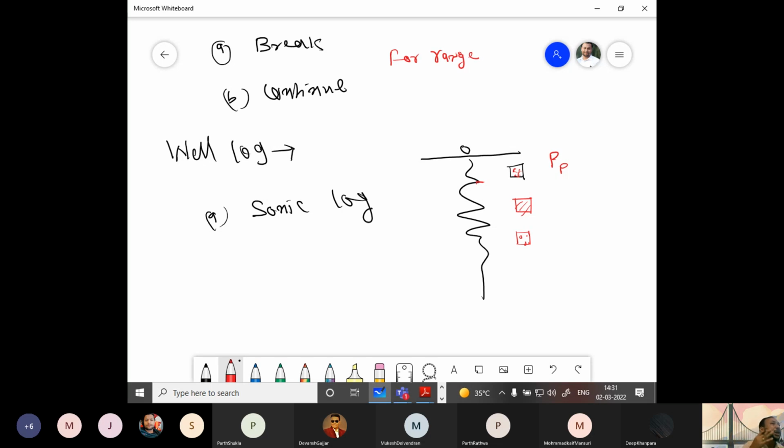We should understand what the pore pressure is. We should understand what the geostatic pressure is. We should understand what the mud weight is, right? If the mud weight is too high or too low, then accordingly the well may collapse, or the fluid may flow through the formations, collapse or maybe fracture. So we need to find out all these things.